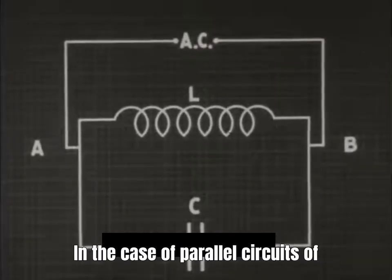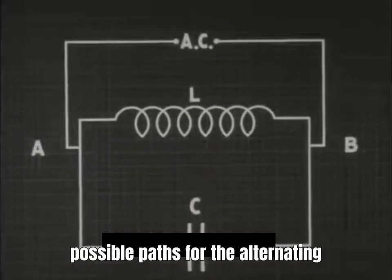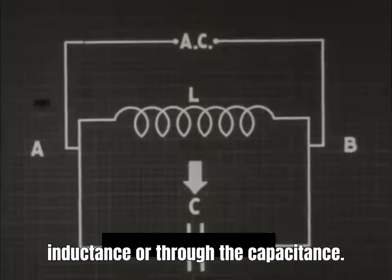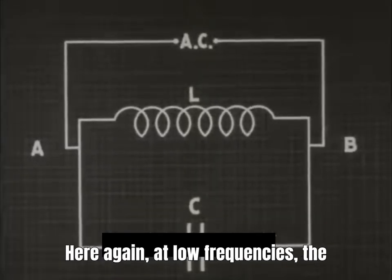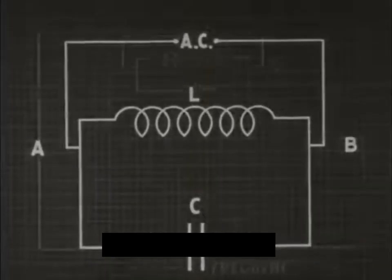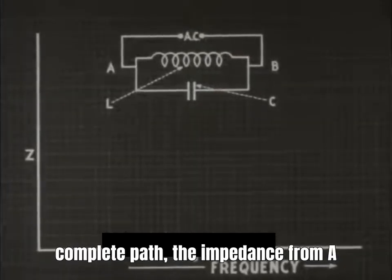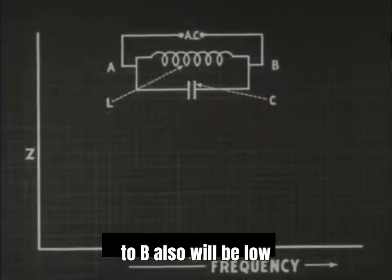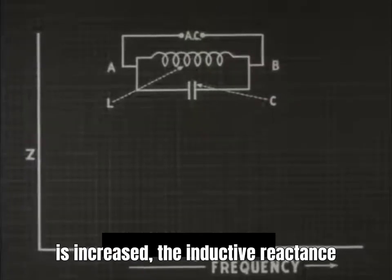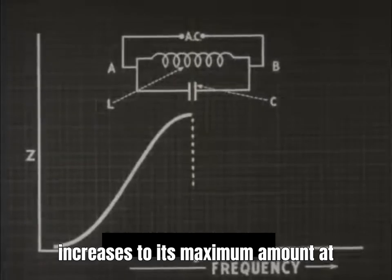In the case of parallel circuits of inductance and capacitance, there are two possible paths for the alternating current to travel, either through the inductance or through the capacitance. Here again at low frequencies, the reactance of the inductor is very low. Since the inductor alone constitutes a complete path, the impedance from A to B also will be low at these frequencies. As the frequency is increased, the inductive reactance becomes greater, and the circuit impedance increases to its maximum amount